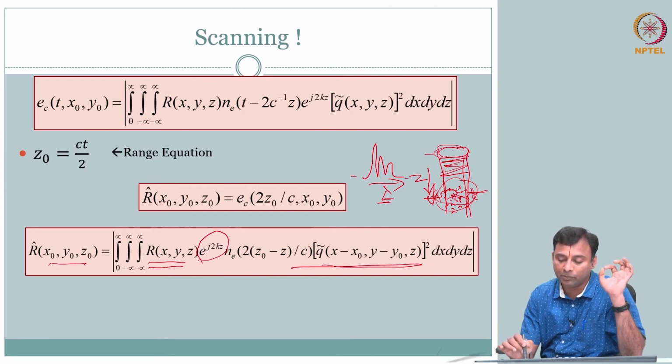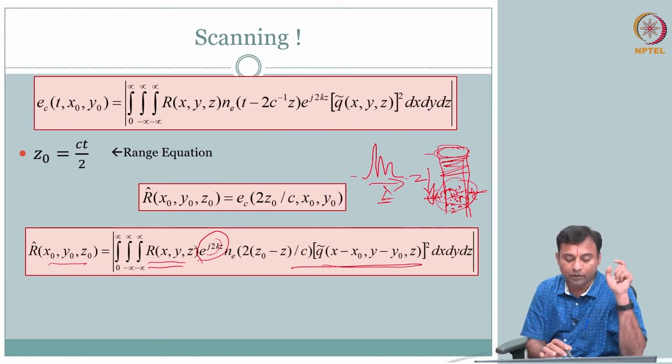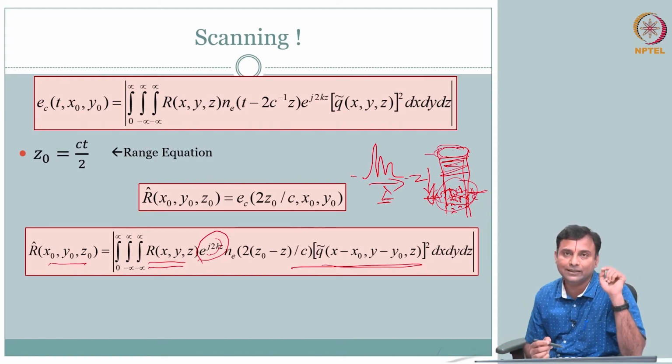Because of the small differences in distances at the scattering locations, when the waves come back, not all of them are in phase. Some can be out of phase, and sometimes they will be in phase. So essentially you have this randomness, because of the distribution of your scatterers within a resolution volume, that can dictate the statistics of the signal that you are receiving. Typically we call this speckle artifact.